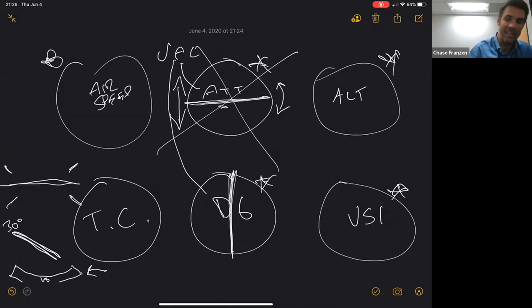Sure. I mean, the inclinometer indicates the quality of the turn. So your slip-skid indicator, that ball needs to be centered. It's really your only indication, instrument-wise, of your yaw condition, of your coordinated condition. Ah, I see. Okay, because I got the impression it was just a backup, and I know it does 3 degrees, but it doesn't really mean much to me. 3, 5, 1. Yeah, so it's important for that ball to be centered.